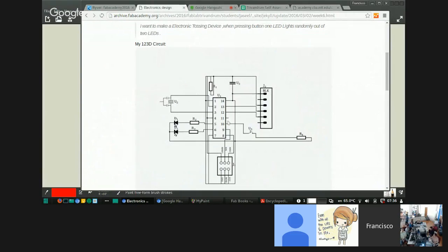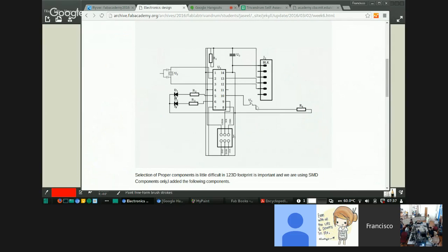So Yasil, you use one through-hole design. So you add 2 LEDs here, one switch. But I don't understand this one. Why are you doing this? Oh, this is the schematic. You are from the other pin. Why are you putting the resistor? This is a 0 resistor. Ah, this is a 0 ohm resistor. And this goes to, you can see in the schematic.